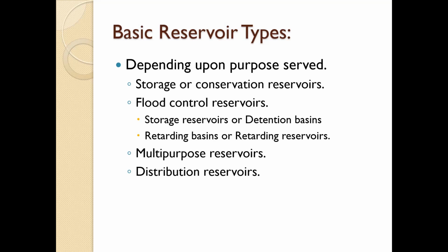As a flood occurs, the reservoir gets filled and discharges through sluiceways. As the reservoir elevation increases, the outflow discharge increases. The water level goes on rising until the flood subsides. The inflow becomes equal to or less than the outflow. After this, the water gets automatically withdrawn from the reservoir until the stored water is completely discharged.